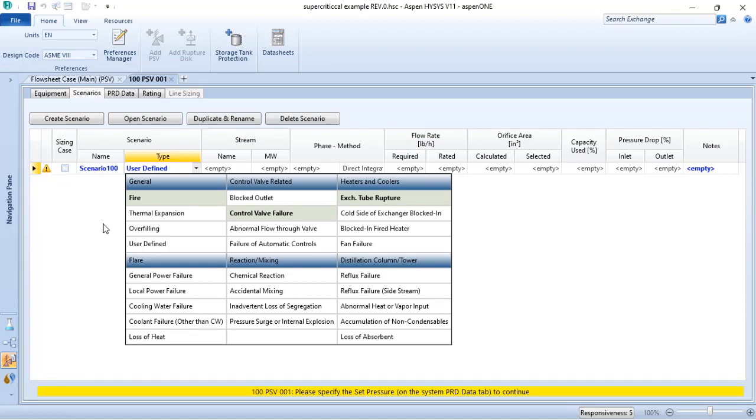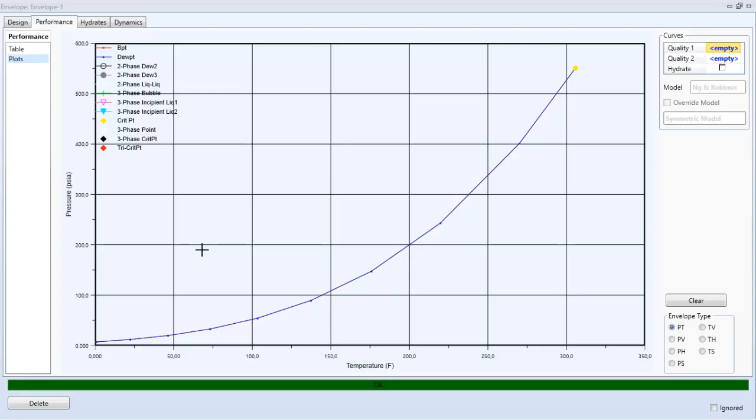There are many others, and what's important to understand in terms of critical fluids is that a supercritical fluid release is not a scenario, it is a condition of a process. And to understand that better, you need to know what supercritical fluids are. In a few words, supercritical fluids are fluids whose pressure and temperature conditions are above their critical point.